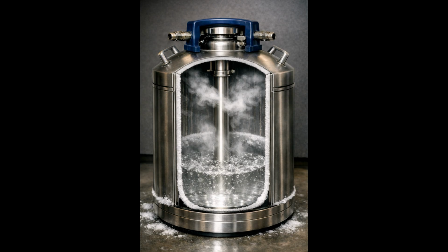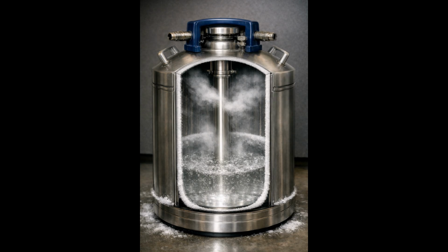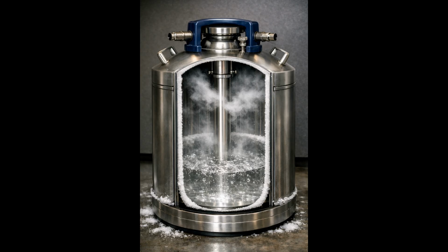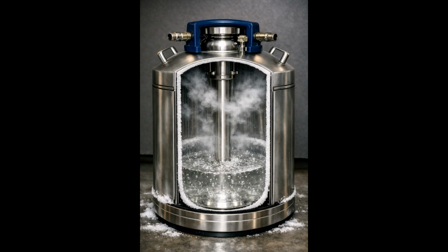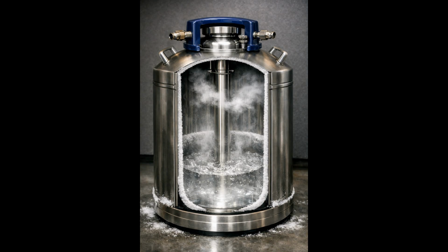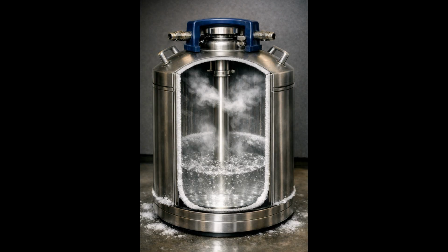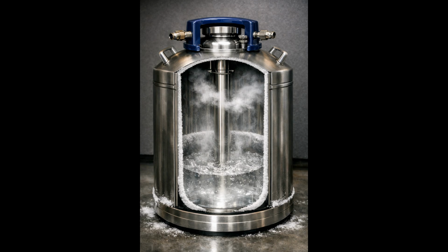Compressibility effects: unlike nitrogen, helium's high compressibility means its volume changes noticeably with small temperature fluctuations. To accurately track transferred helium, we must account for both liquid and gas displacement during the process.